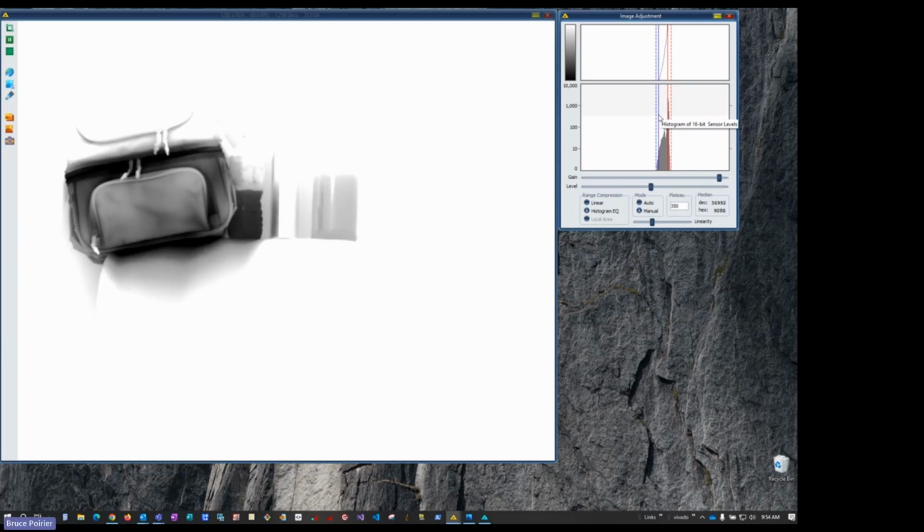When you do manual adjustment in histogram mode, it basically ignores all values that are above the red or below the blue line and calculates the histogram only within that area. So you still get a nonlinear transfer function, but it's constrained to this area that you've marked by doing manual adjustment. Not that useful, but we put it in for completeness.